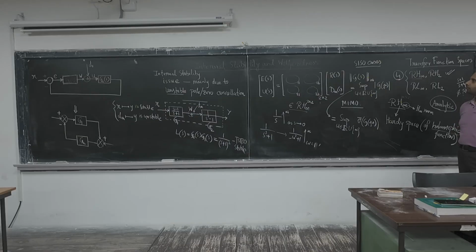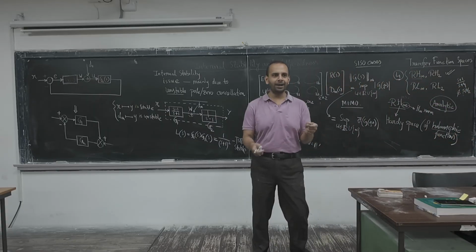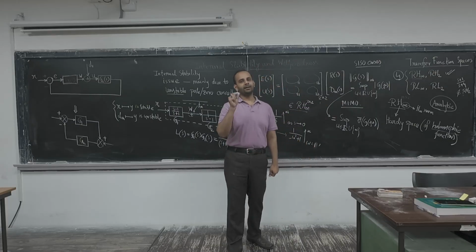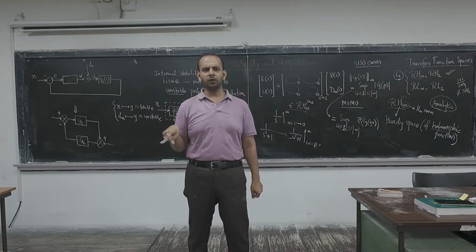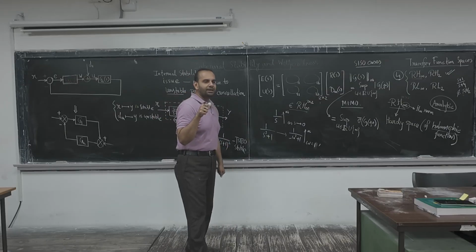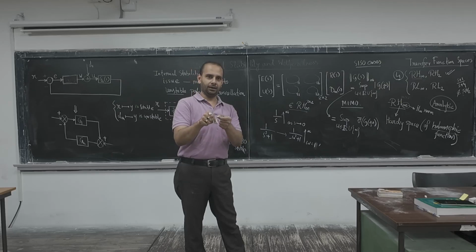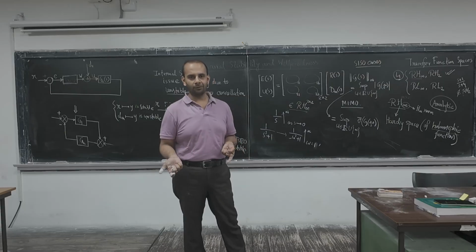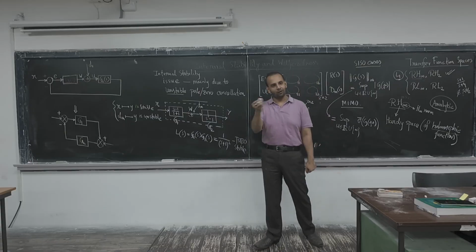Yes, because when we write y of s equals g of s into u of s, the input is getting multiplied by another quantity and we get the output. Now in the time domain, there are many functions in between, like e to the power something, then integration, and so on. So we don't directly get the feeling of the input being multiplied by a gain. Ultimately they are the same, because it is the Laplace inverse of y of s, but in the time domain, mainly because of the convolution, we don't get the feeling of the gain.